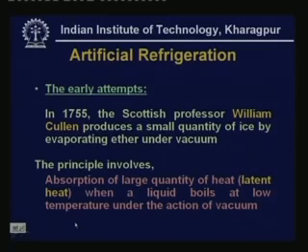You can see that this process is not a spontaneous process, because some external effort is required to maintain the vacuum. That means you have to have some vacuum pump, which requires some mechanical energy input, so that continuous vacuum can be maintained in the bell jar. So this is not a spontaneous process, and it is also not very useful in practice, because once all the ether evaporates, then there won't be any refrigeration.